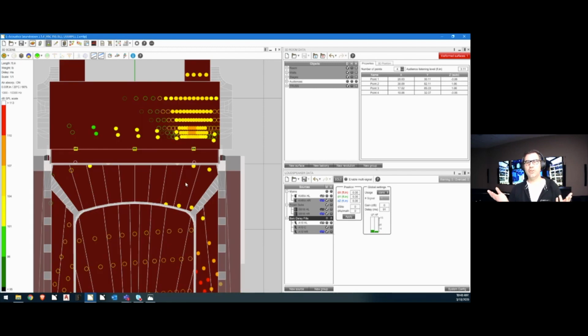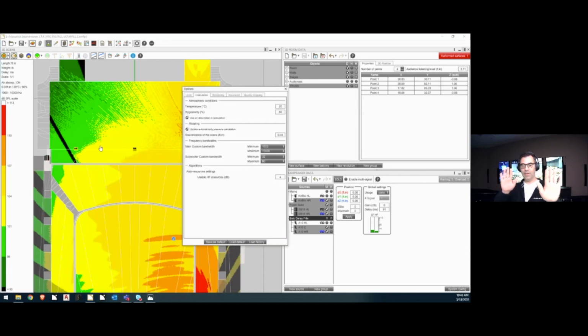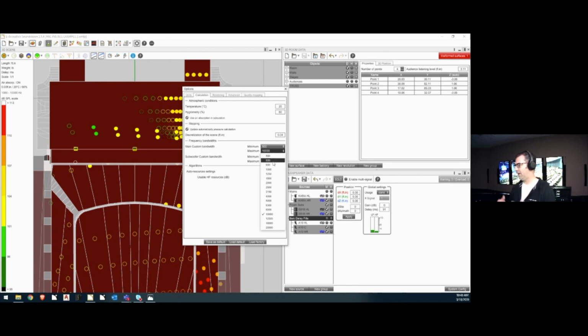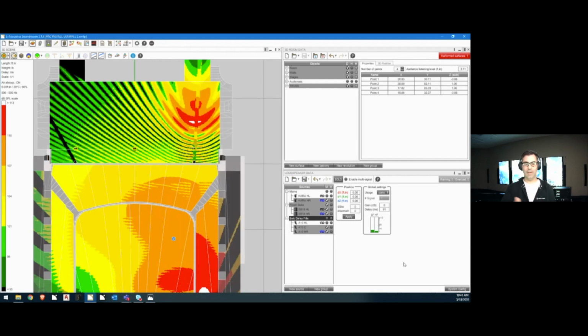Yeah, what you could actually do if we really wanted to amplify this, if you want to flip to like 500 hertz only, something crazy. Sure. And that's where you'll really obviously see the difference. So if you imagine having 2 speakers both doing 500 hertz, if they're offset by a millisecond, it's a really obvious comb filter. If they're offset by 91, you effectively have 2 very distinct arrivals, and it's chaos. And that's one thing you can actually play with in Soundvision. You can use this tool to help understand how those comb filters interact, how time alignment becomes so critical and important, and so on and so forth.